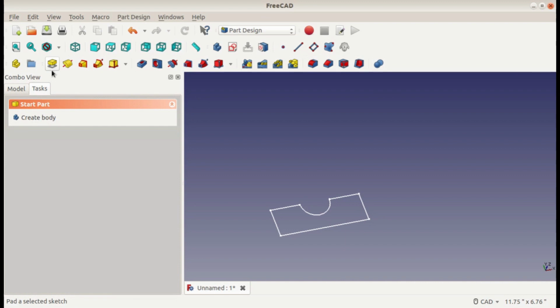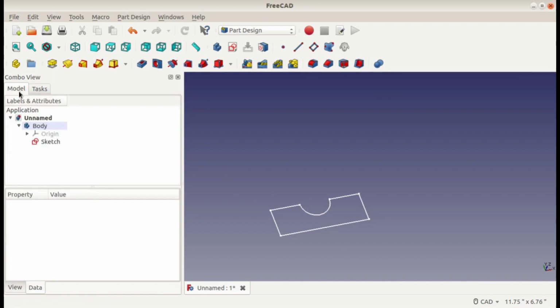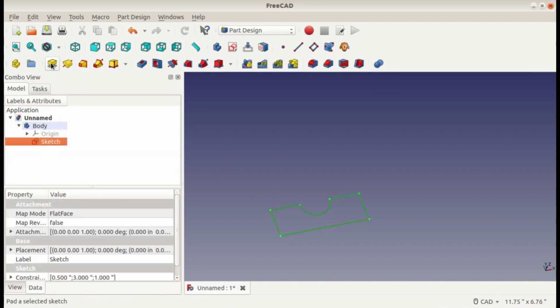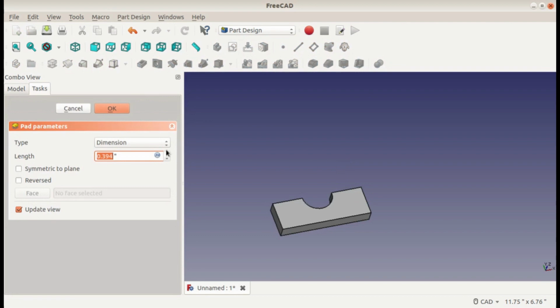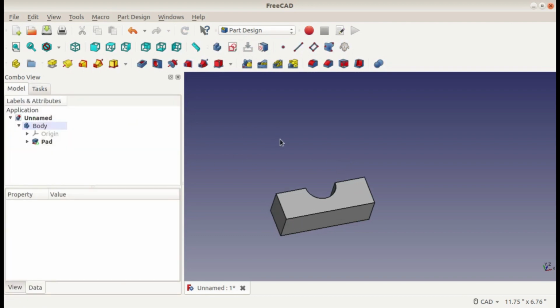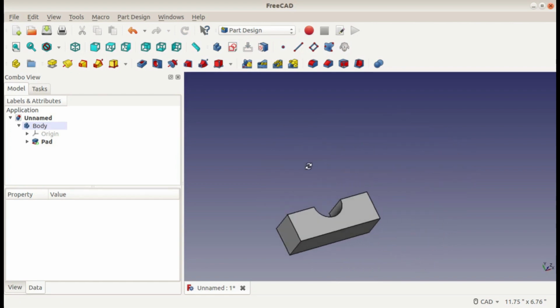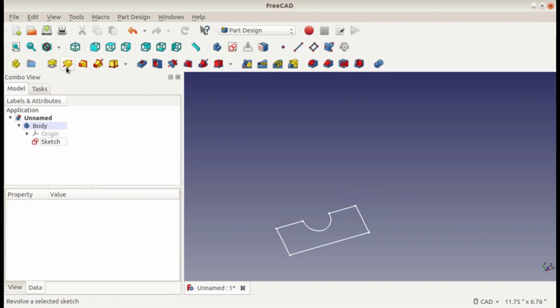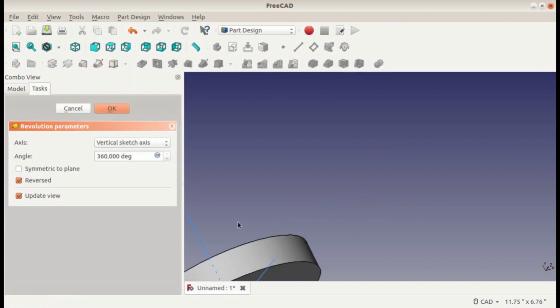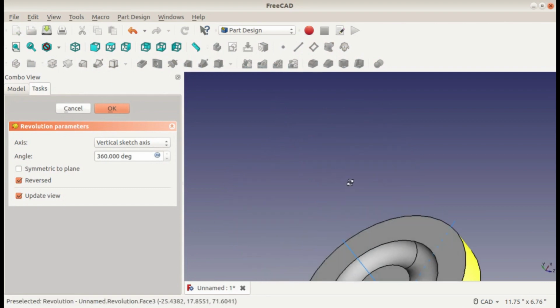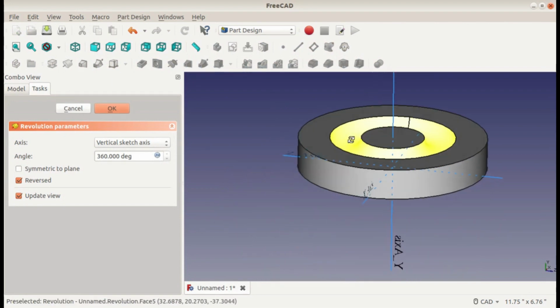So normally you're probably going to use the Part Design here for a pad like this. Now you have your part. I'm going to go over one more type of extrude in this tutorial. This is just the regular linear pad extrude. But if we delete that and instead choose the revolve extrude, this is completely different. Now, we still have our sketch.